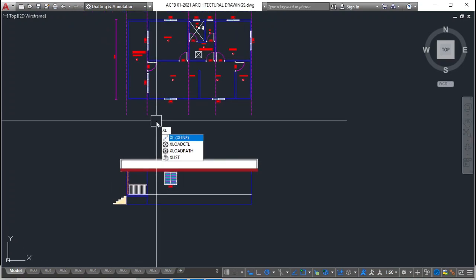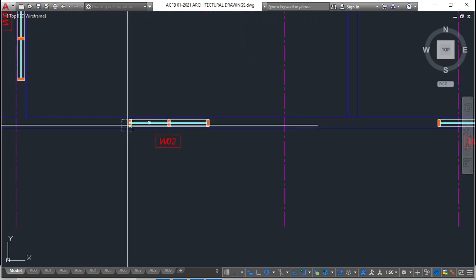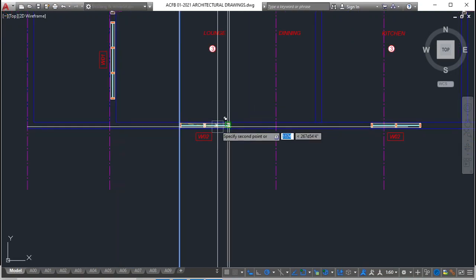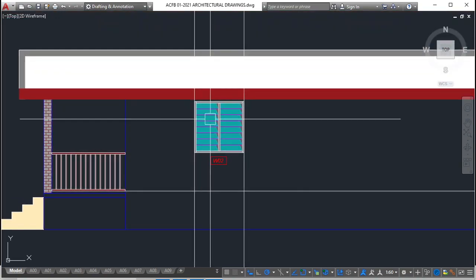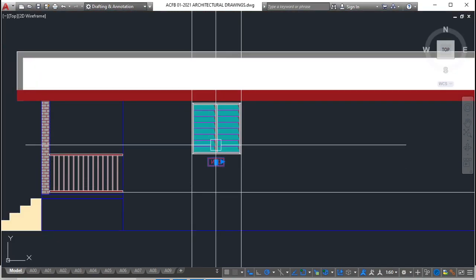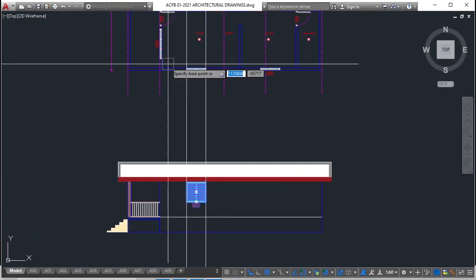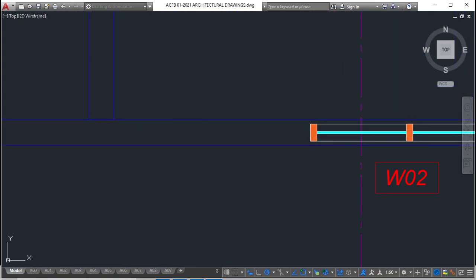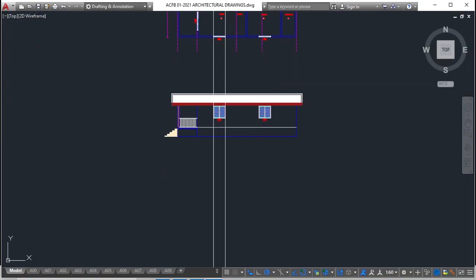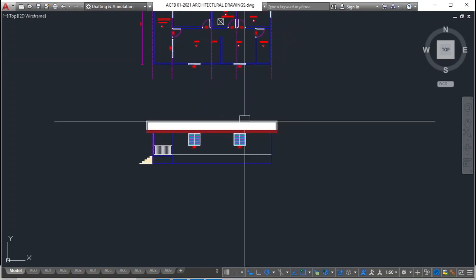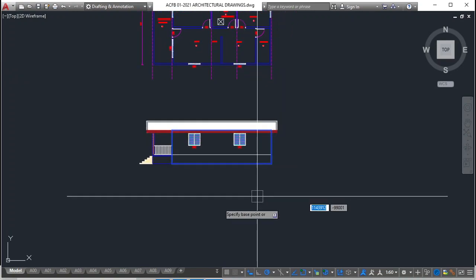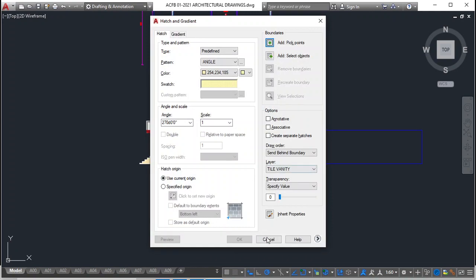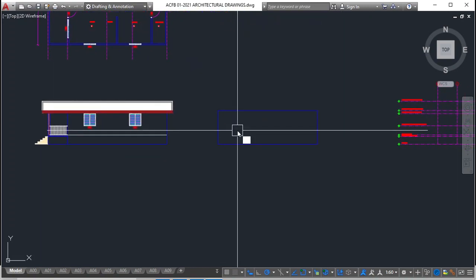So as per usual, we'll create a construction line. Then we'll put it on our outline. Then we'll copy it to one side only, like so. And since you have already set it up properly and it's already in place, we'll just select this and we'll select this. Copy. Take one of the base points. I'll take this corner here and just move it that side to make your windows and your text look consistent with the elevation on top. Now what we'll do is just copy this outline outside. Take a H for H, then press enter.